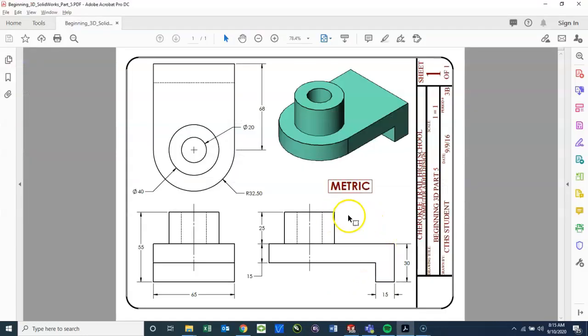And so lastly, what we need to add is this piece right here at the very bottom. Now there's a couple ways we could do this. We could start with a sketch on this surface and draw a box and then extrude it through. We could choose the underside surface and draw a rectangle and extrude it down.